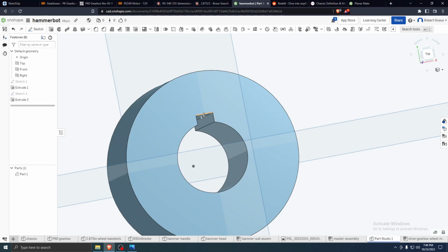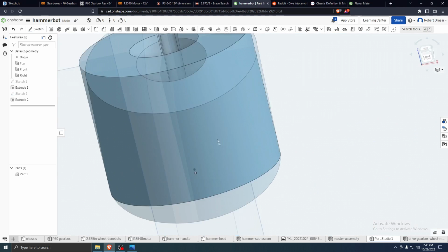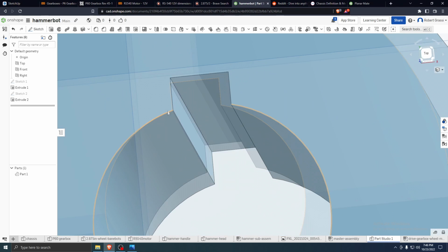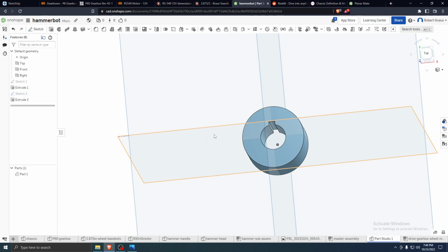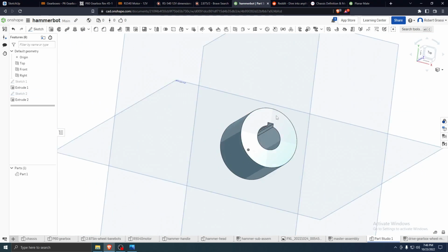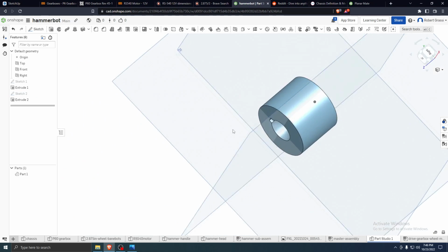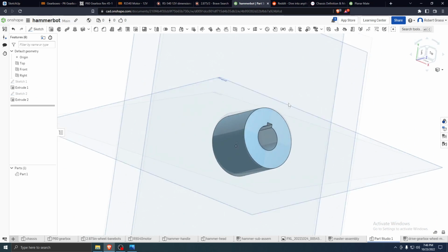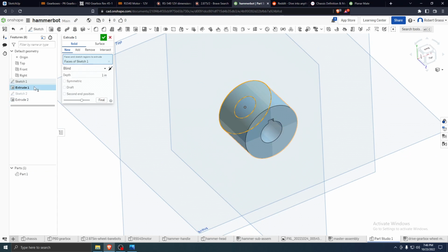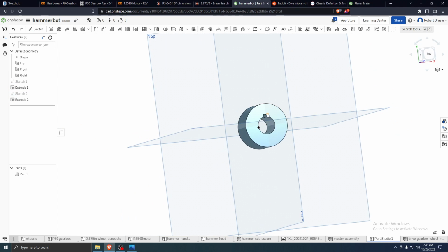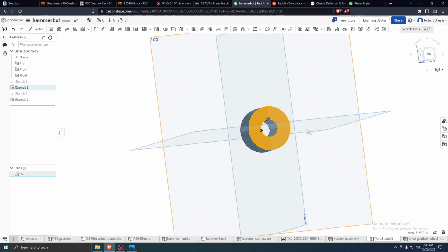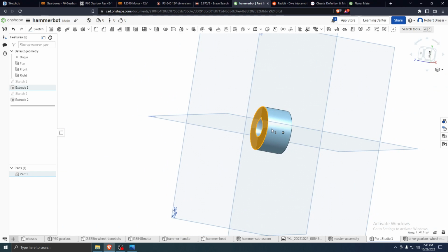Good, good. Alright, I'm pretty sure we can force it. Whenever you 3D print stuff, sometimes the plastic over extrudes so that internal dimensions will be a little bit smaller than they are in the CAD program, but you should be able to just kind of snap it in there, force it in there. You can always print another piece, so. And I think I'm going to change thickness back to 0.75. Yeah, that's good. Okay. Now this has to be attached to something that's going to hold the hammer.